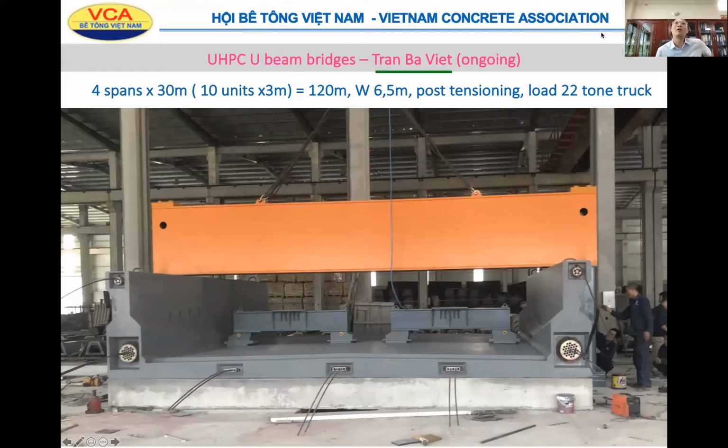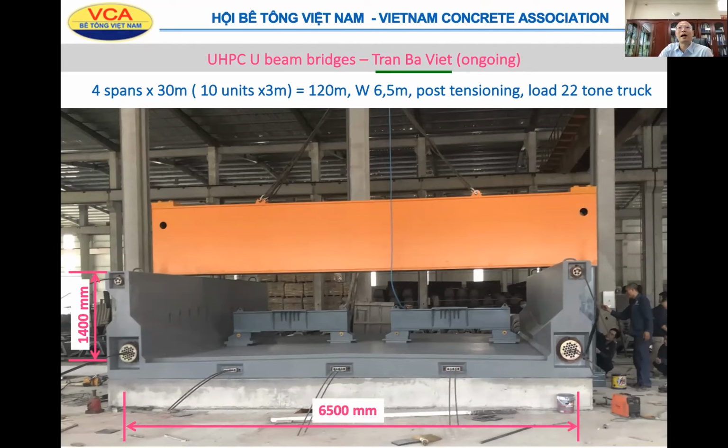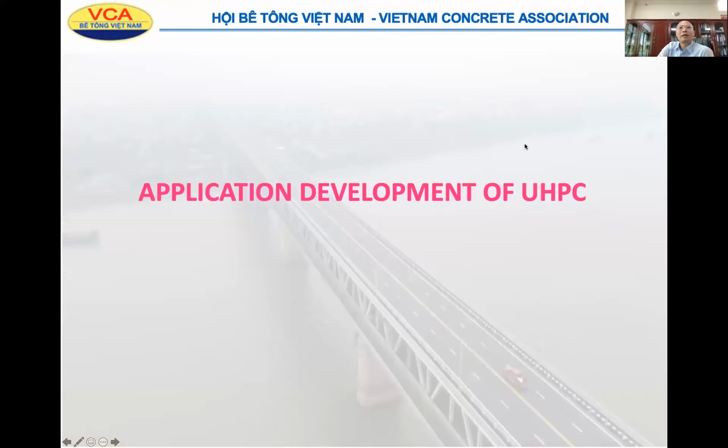And another research ongoing implemented by Dr. Phạm Việt. He tried to use UHPC for a U-beam bridge, and the longest and the largest one, Dr. Phạm Việt is carrying out the research. That's a 120 meter length bridge, comprising actually 4 spans, and each unit is 3 meters in length, and the width is 6.5 meters and 1.4 meters high. So he tried to do post tensioning for this, and he predicts that it can carry the load of a 20-ton truck for this beam. Right, that's the research situation.